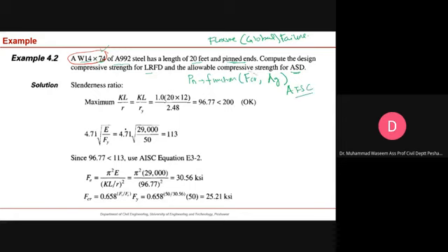And the critical stress, you need to estimate critical stress. Okay, but in order to estimate the critical stress we have two types of formulation. For that we have to check this limit. First you need to calculate this ratio, slenderness ratio. Now for the slenderness ratio, you have to calculate the K value, for the pin ended condition it is 1.